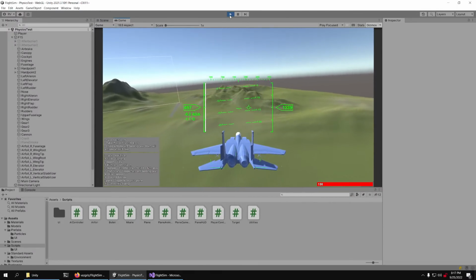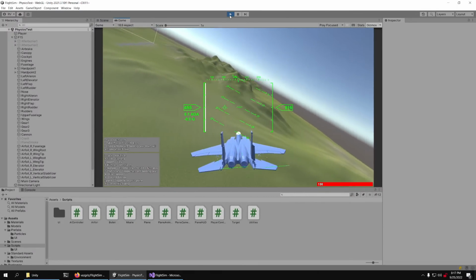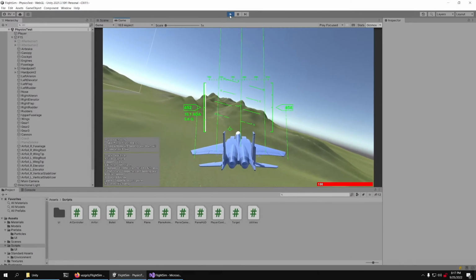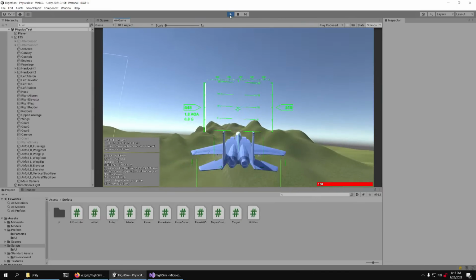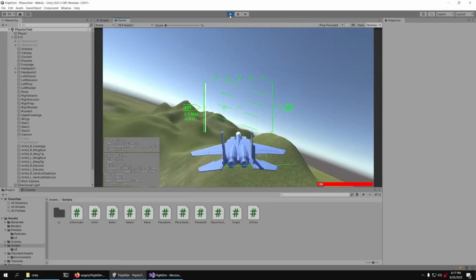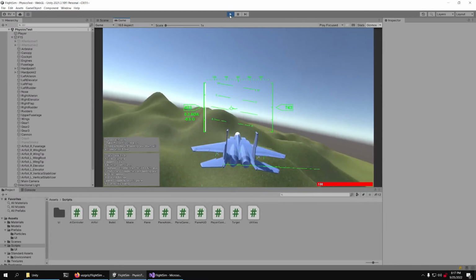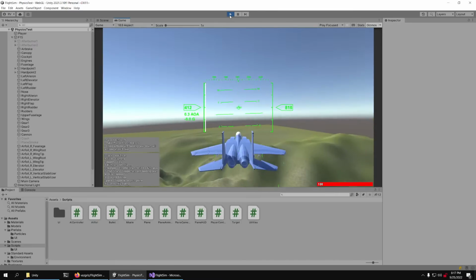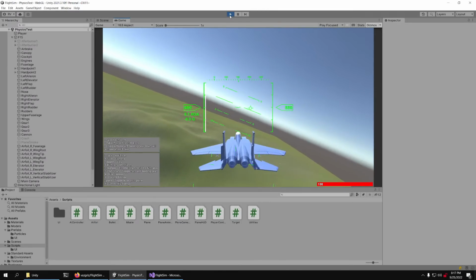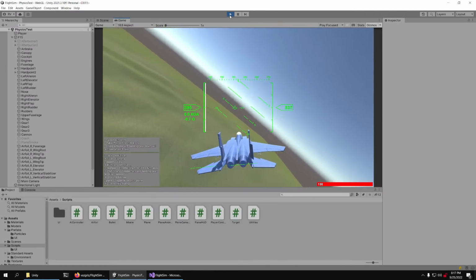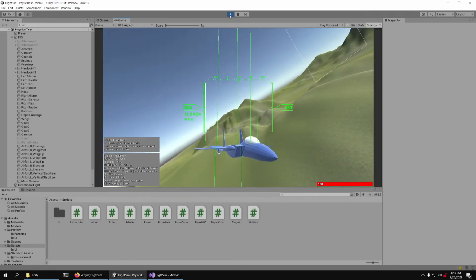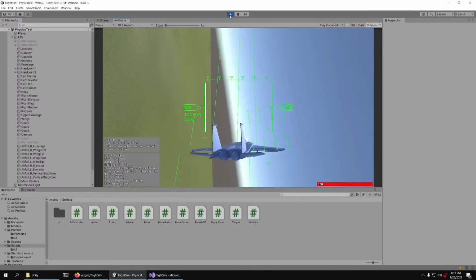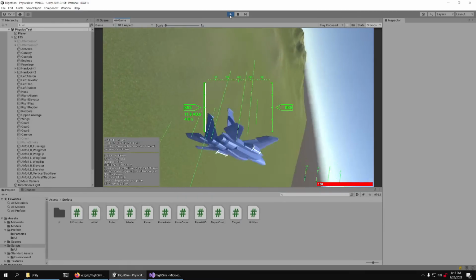However, it doesn't seem to actually change the amount of lift generated by the wings, just because the rudder isn't pushing the nose to the side far enough for the wing sweep to change. But yeah, this is a very complex system where the rudder wants to roll in one direction, but the wings want to roll in another direction. There are so many different forces acting on the plane at the same time.